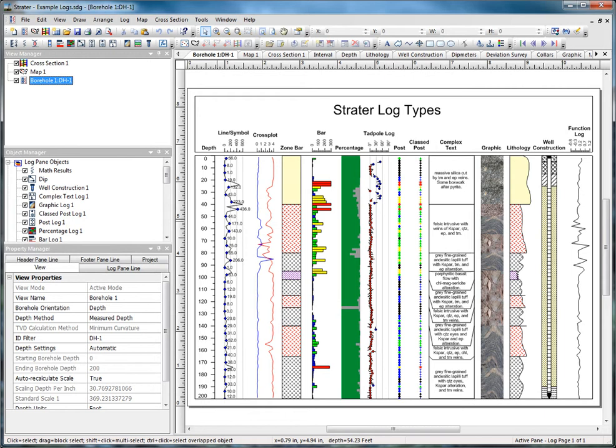There are three ways to enter inclination and azimuth data. A single set of azimuth and inclination data can be entered for each borehole in the collars table. The azimuth and inclination data would apply to all points throughout the borehole. The deviation or survey data does not have to have the same sample interval as the wireline or depth interval data. Azimuth and inclination data can be entered for each data point in the borehole directly into the depth or interval table as additional columns with the rest of the borehole data.